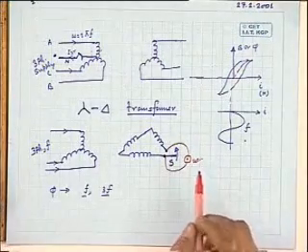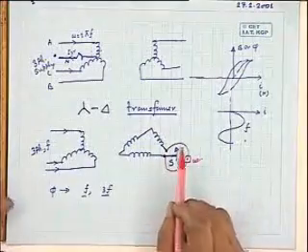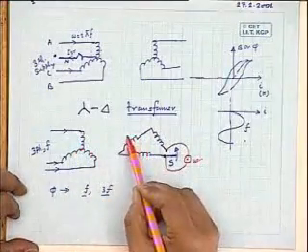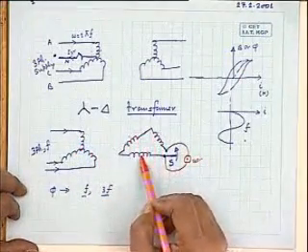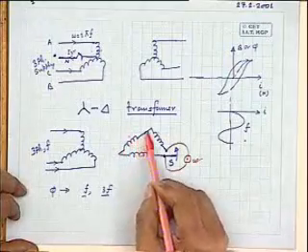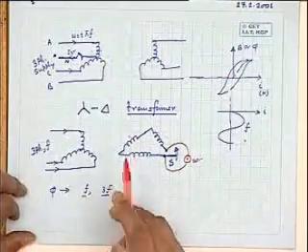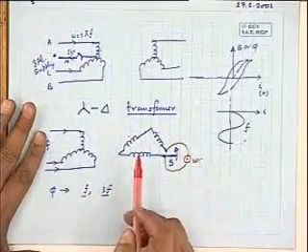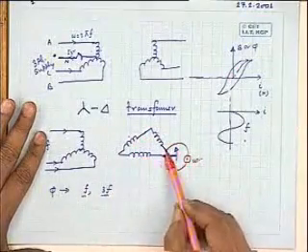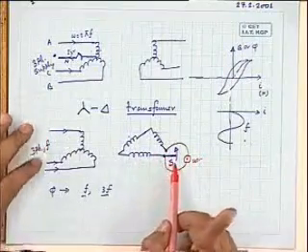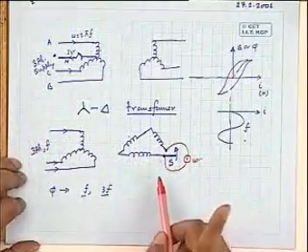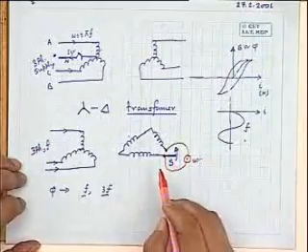It will be of the third harmonic voltage, it will read. Why? Because the fundamental frequency voltages will be induced, VA, VB, VC. And of course, this series connection I have done correctly with due regard to proper polarity. And suppose let us assume only fundamental frequency exists. Then what is this voltage? This is 0. Sum of all the balanced three-phase voltage will amount to 0.